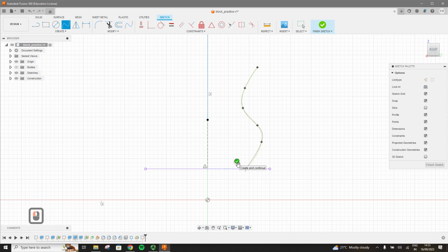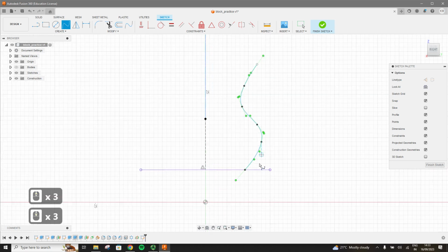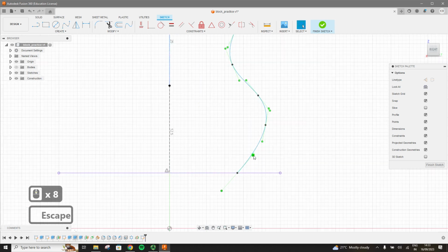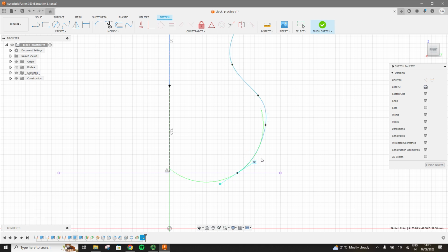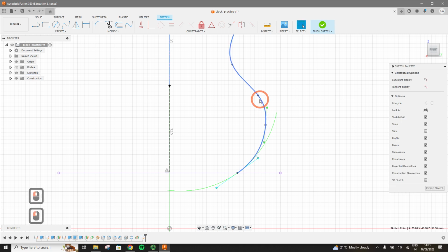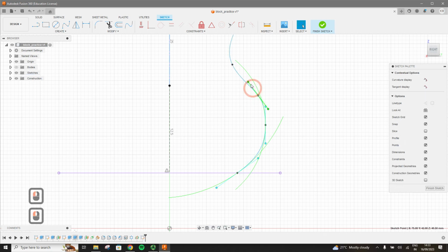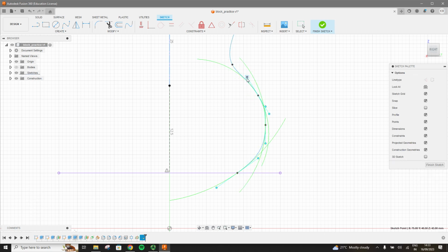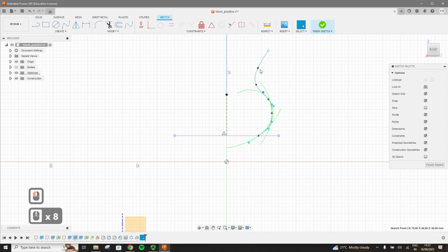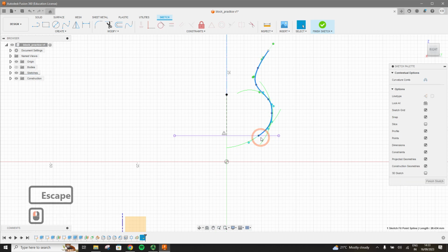So this is the spline command that we saw. One thing we didn't see at that time is that we can manipulate each of these points after drawing it. So for example, if you want this to be at a more angle, you can control this. You can change the tangency, the magnitude of the tangency, and you can do it for every point actually. So you can either modify it later, or you can remake it by changing the control points. Okay. I'm not particularly aiming for any specific shape right now, but I just wanted to show you that.